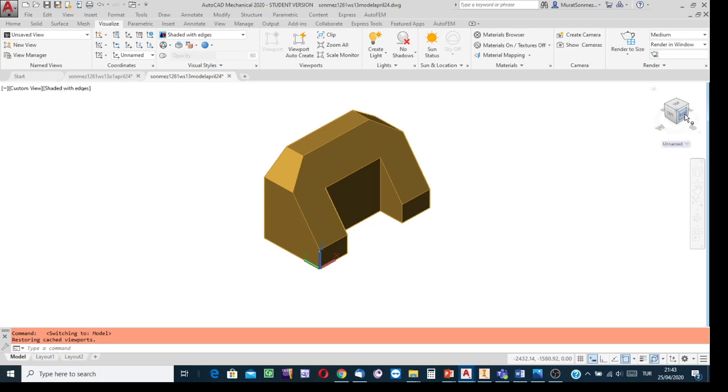Although, let's say, it is written left on this surface, but it is parallel to the front side of the model, the front side of the object, then at the view creation stage, from the list, I would select the left option. But here in this example, the front side surface of the cube is parallel to the front side of the object. So to teach the software the orientation of the object, from the list select the front option.